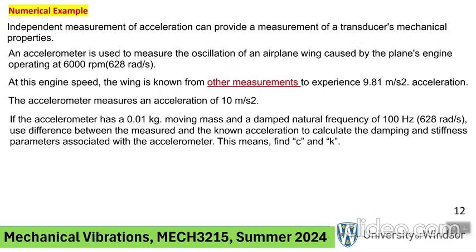Actually, to get the damped natural frequency, you don't even have to do the logarithmic decrement. That is not needed. If you just want the frequency, you just look at the plot generated, for example, on the oscilloscope or whatever of your device, which is freely oscillating, and you get a graph, and the distance between two peaks is the damped natural frequency.